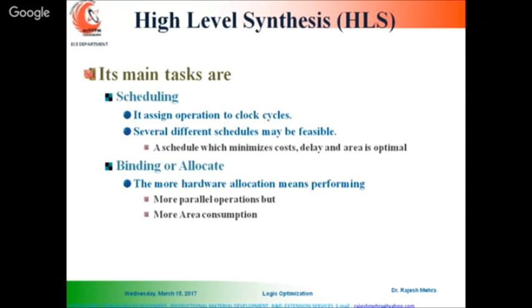You have to schedule it based on clock, right? And some parts need to be performed first, some parts need to be performed after the first one. So based on your requirement, you have to schedule your part based on clocks, and you have to take care of cost, delay and area. So your scheduling should be in this way. So once this scheduling is done, then you go for binding.